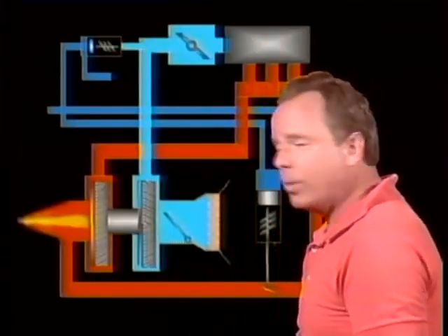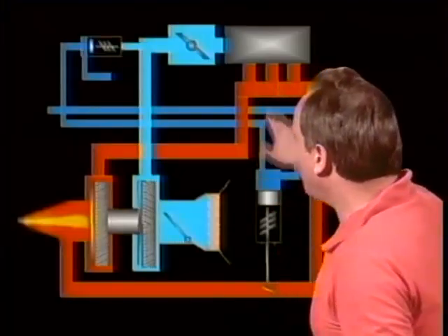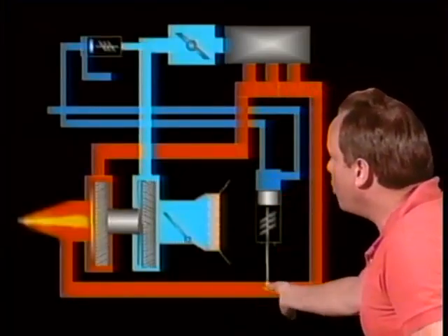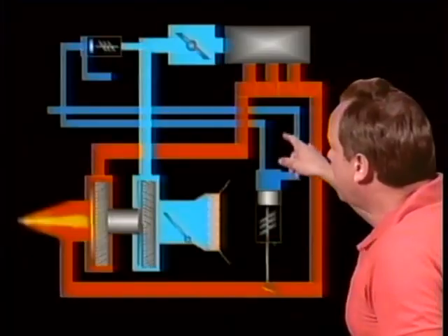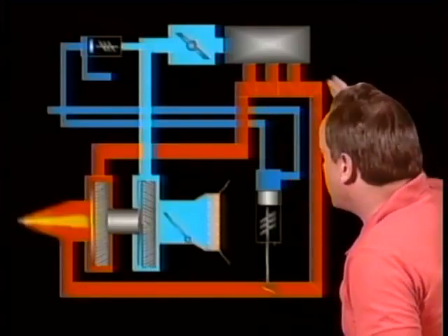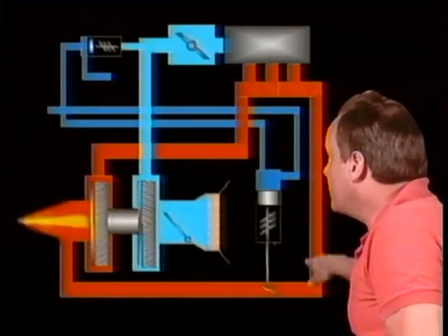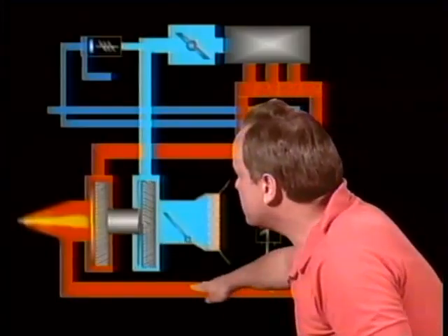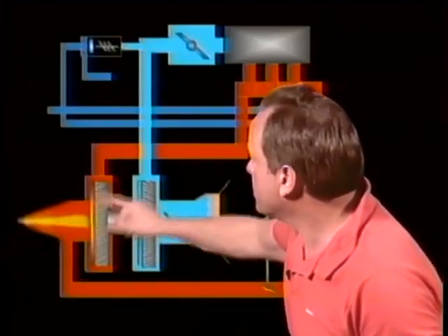That's a turbocharger. By the way, if you have a turbocharger equipped on an aircraft and you don't want to turbocharge at the time, you have a wastegate down here in the exhaust system. You open this wastegate, and the exhaust, instead of running past or through the turbine, goes around or bypasses the turbine because the wastegate's open, and that's the easier route for the exhaust gases to flow. And so you bypass the turbine, and the exhaust goes out without spinning the turbine.